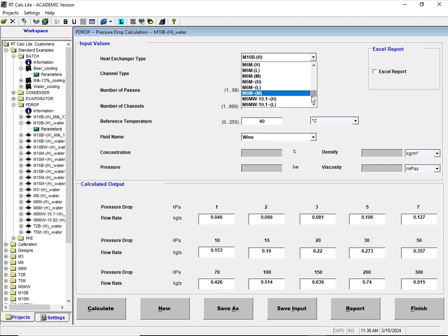All right. But when you get up to the top end, these are brazed plates based off another manufacturer. Okay, and they're brazed, and the response is different. What you can do with a brazed plate is a little bit different to what you can do with a gasketed plate. With a brazed plate, for instance, we don't like to go multi-pass. In other words, you kind of packing one exchanger linked to the next. The flows go backwards and forwards, up and down, up and down. We don't do that with brazed because it's quite complicated to do all the routing. So the brazed are kind of very simplified, one straight through type constructions.